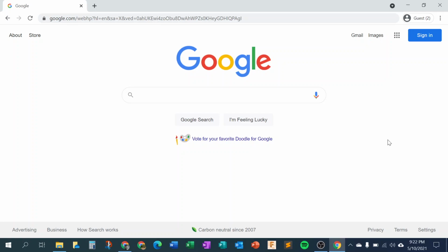Okay, so I'm here to do a demonstration video for Dave and his kids in his shop class, that recently purchased a 3D printer, a Creality Ender 3. And I'm just going to do a basic video on how to download an STL off the internet, pull it into Cura, and slice it so that you can upload it to an SD card and push it to your 3D printer.